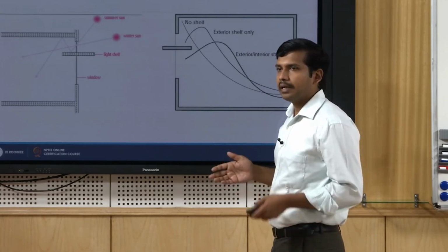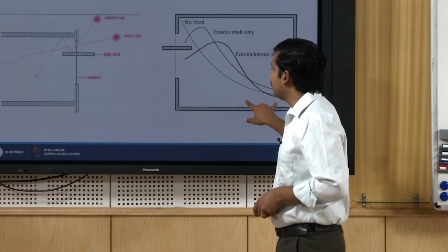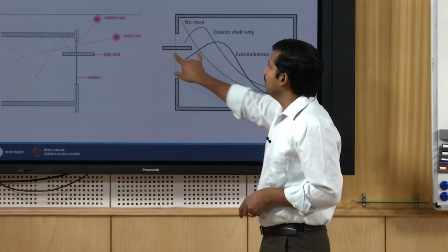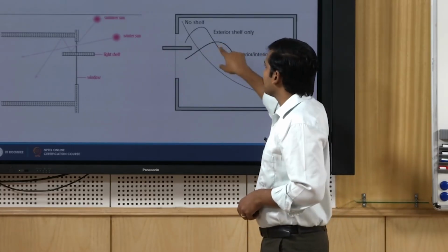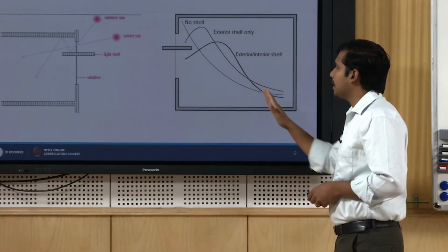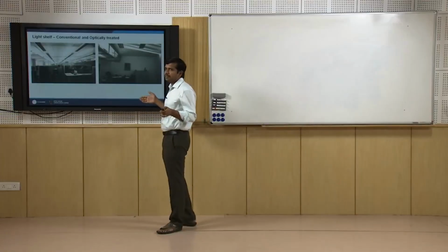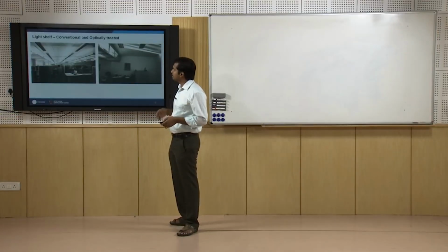It is also not right practice to get an excessive amount of light in the periphery and make the interior too dark. So ideally this type of light shelf extending into the interior of the building will give a fair distribution, at least for two-thirds of the room area. It depends on the fenestration size and the depth of the system itself.